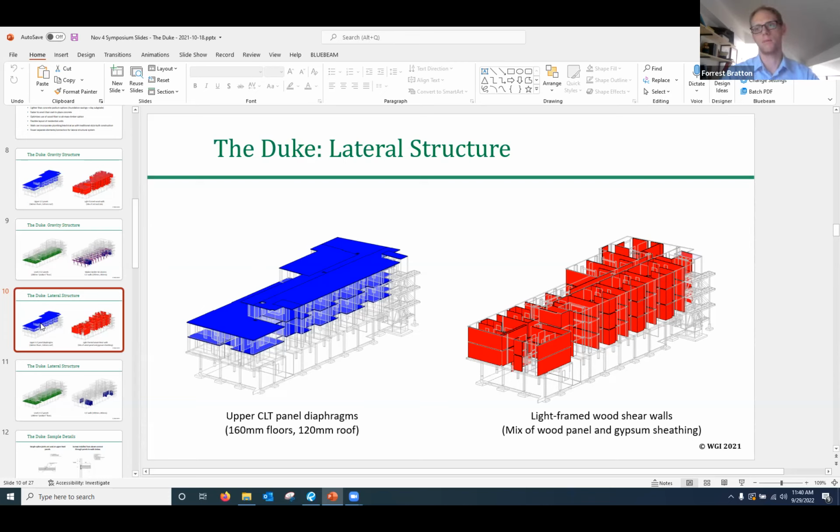And the other is that it becomes similar to a concrete structure for multifamily, where you've got a podium structure. We have to know as a structural engineer where all those penetrations are being located in that concrete slab, so we can evaluate the structural impact. And so it becomes a similar process for each of the floors that we're putting plumbing penetrations through, that we're spanning with CLT, to be able to have that back and forth with MEP on where those can go, where they don't affect structure or don't affect it too much.